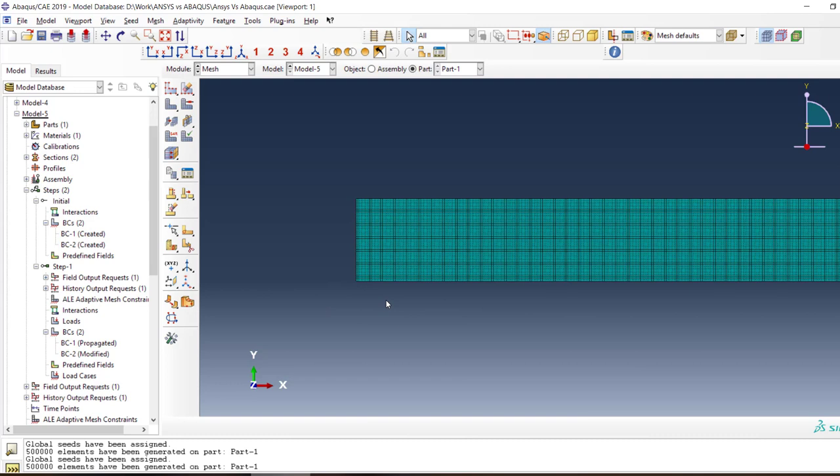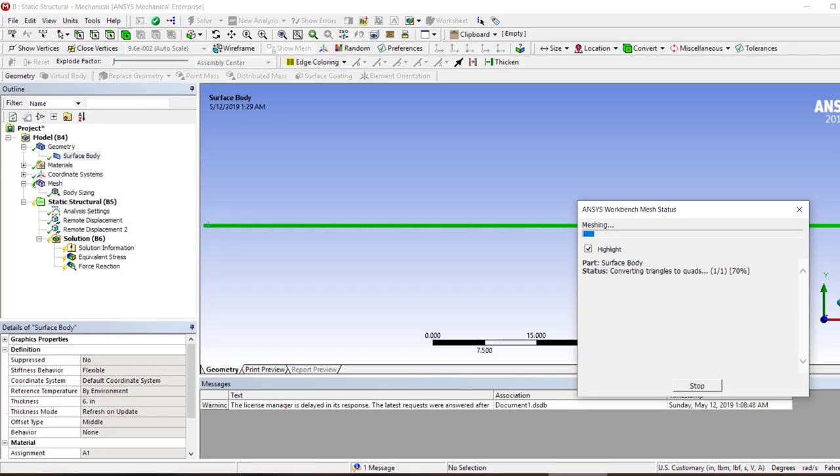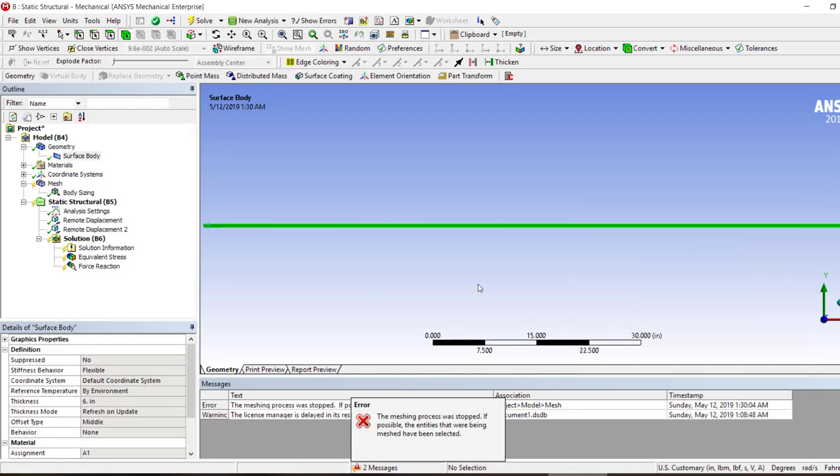Now if I have a truss, or a structure that needs to be modeled, I would rather have it modeled in beam elements rather than in 2D or 3D shell mesh. So yeah, it's still creating the mesh. That's too much time. So let's finish it and then we can try it using the 2D plane stress problem.